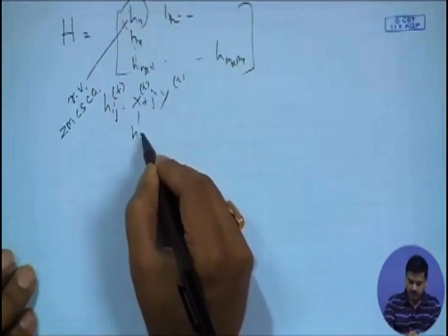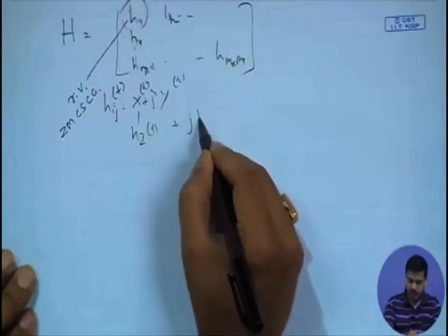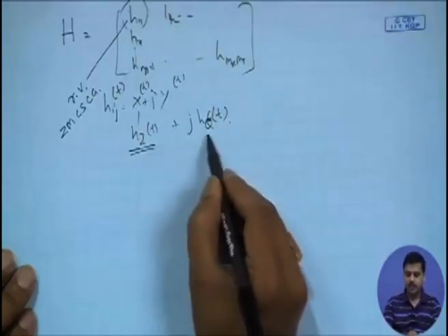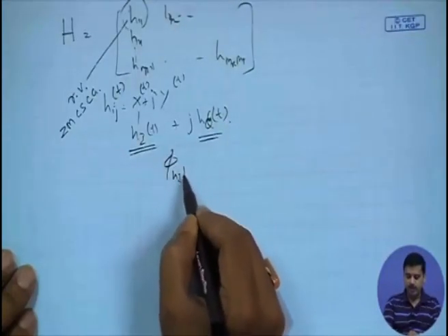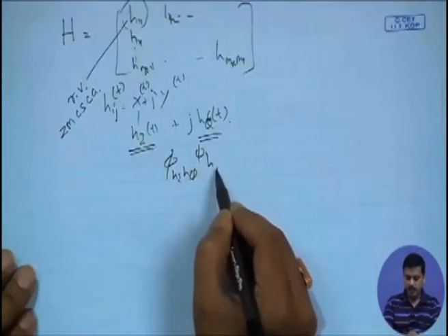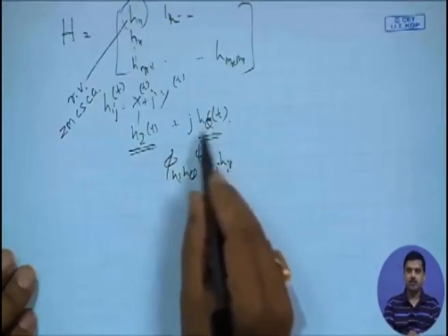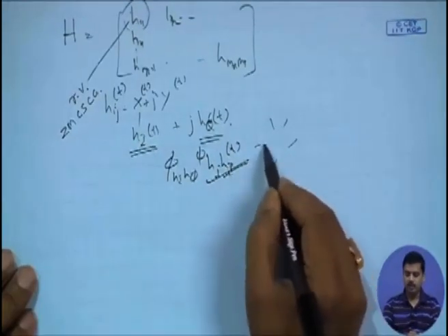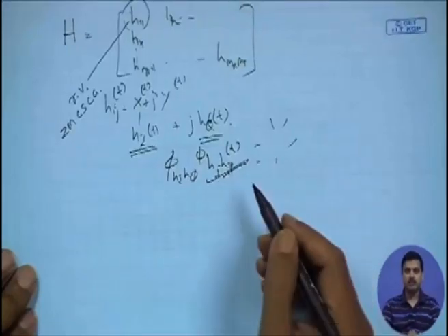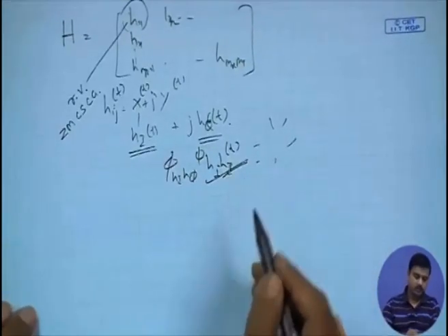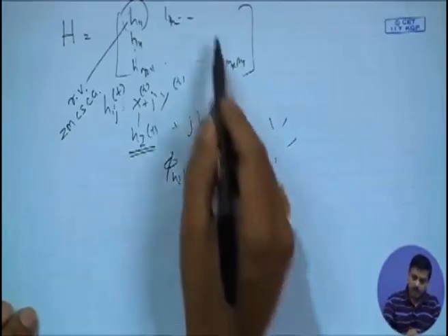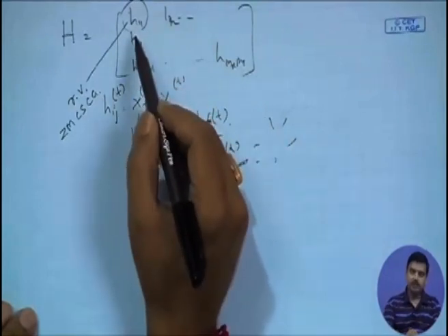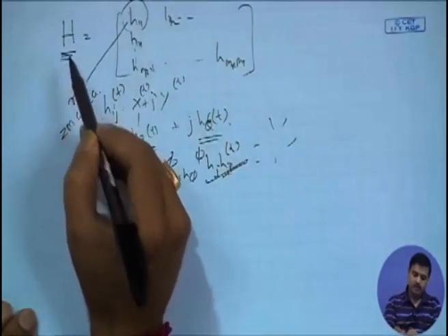So basically this is H_I of t, what we have studied before, and this is H_Q of t. So we have studied the properties of H_I and H_Q, we have studied all these properties, and we have found this follows the Jakes spectrum when there is equal angle of arrival, otherwise there is another spectrum, Rician spectrum, and so on and so forth. So what we essentially want to say is that this contains random variables which have been very well studied, so this itself is a random matrix.